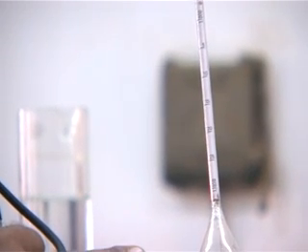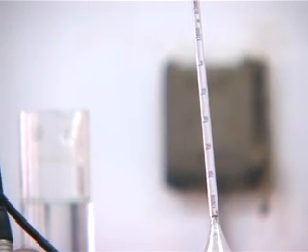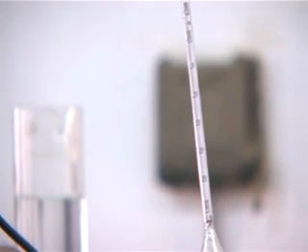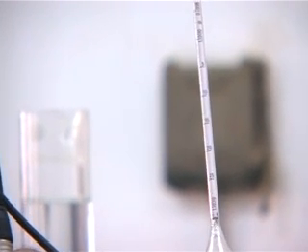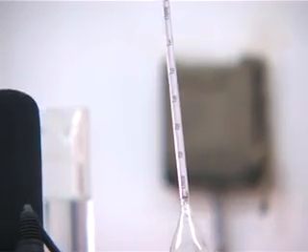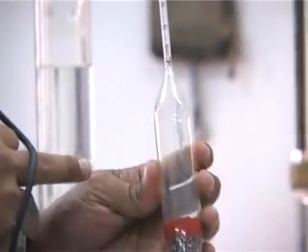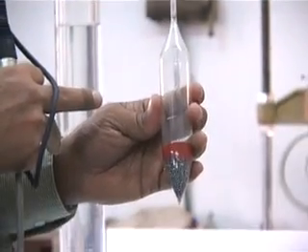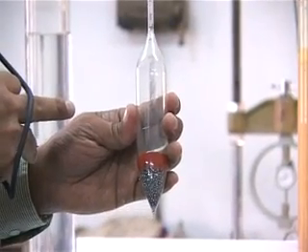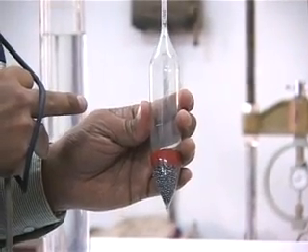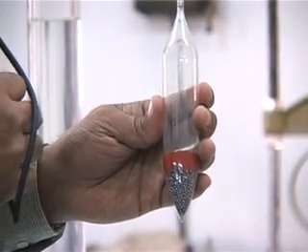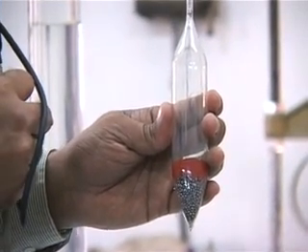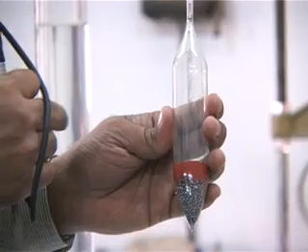From that reading we can correlate to the specific gravity of the slurry at the center of the hydrometer bulb, and from that we can find out the representation of a certain grain size within the soil sample using Stokes' law of settling spheres, approximating the soil particles as settling spheres.